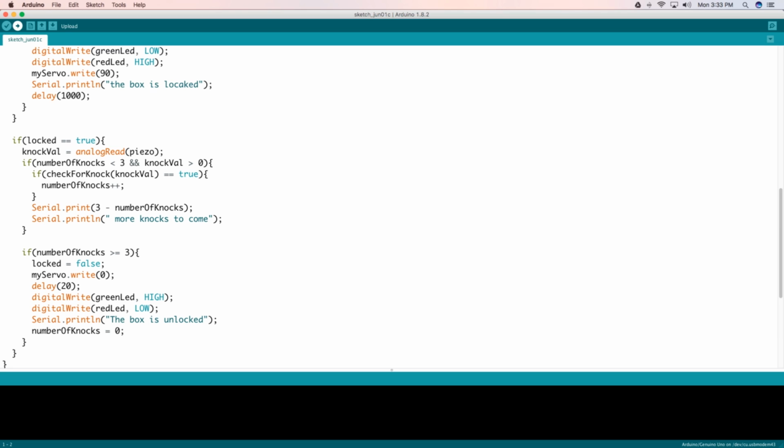If everything goes well, it'll just go up there, and if there are any failures, the IDE will kick back with whatever line the error is on, and you can go see. For me, most of the time, my biggest problem is I always forget the semicolons. But it'll tell you that. So that's the nice part: if there are syntax problems with the code, it will fail out before you upload it. So that's the good thing. You don't have to worry about your Arduino failing because you forgot to put a semicolon somewhere.